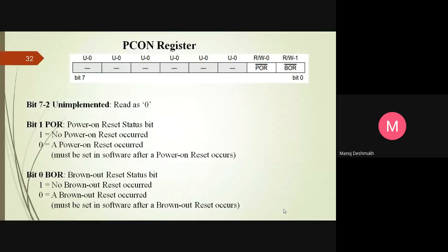So in today's lecture, we will discuss the next SFR, and today's first SFR is PCON, Power Control Register. In that, only 2 bits are used now, and the remaining bits are not used, but they may be used after modification in architecture or adding some additional bits to these SFRs. So till now, we will discuss these 2 bits available in PCON, that is power control register,